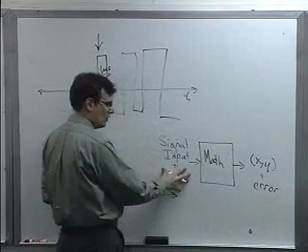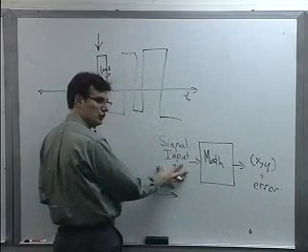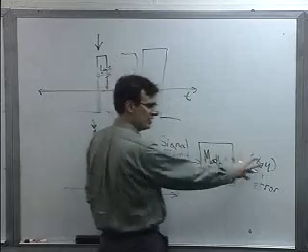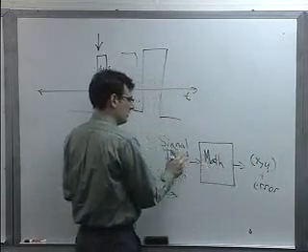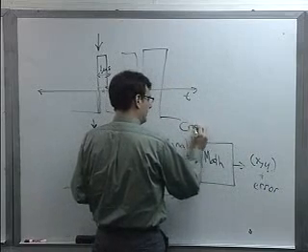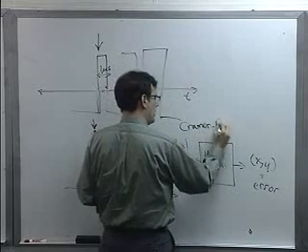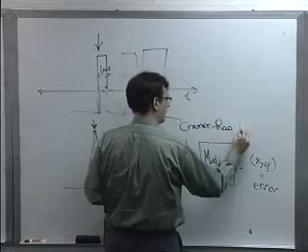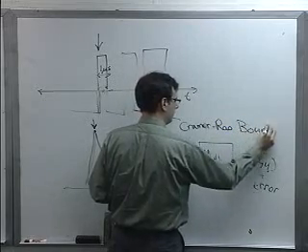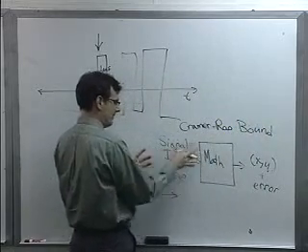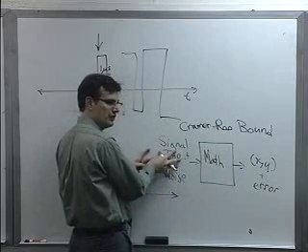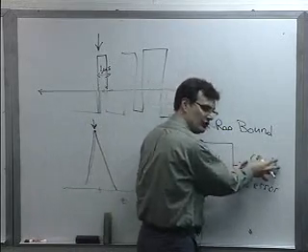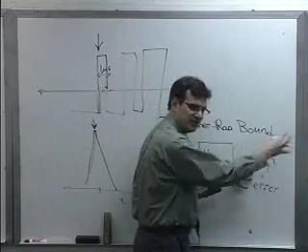If there was no noise or uncertainty in this measurement, there wouldn't be any noise and uncertainty on this measurement, right? So the Cramer-Rao bound is a way to rigorously map. If you know the math that's going on here, you can take the uncertainty in your signal and map it to the uncertainty in the output. And there's a standard technique for that.